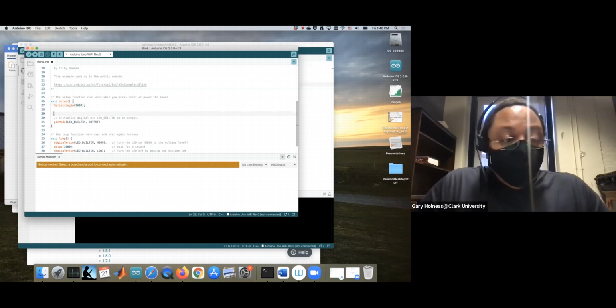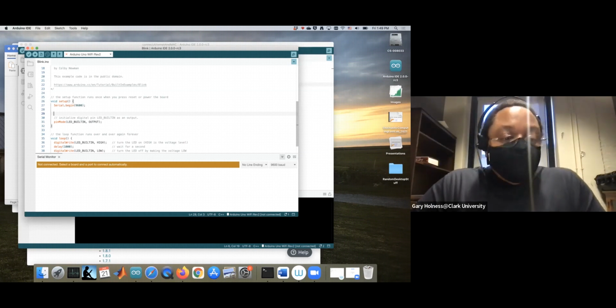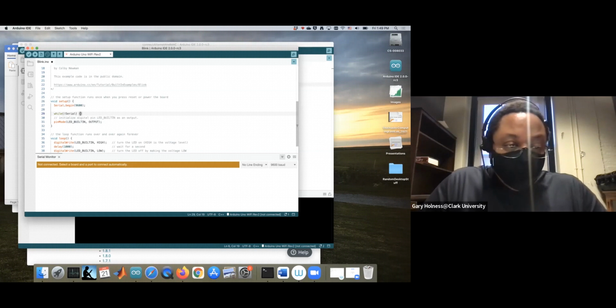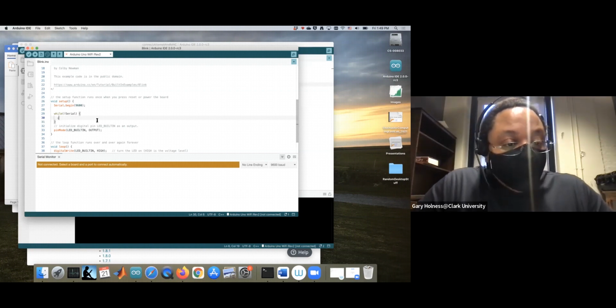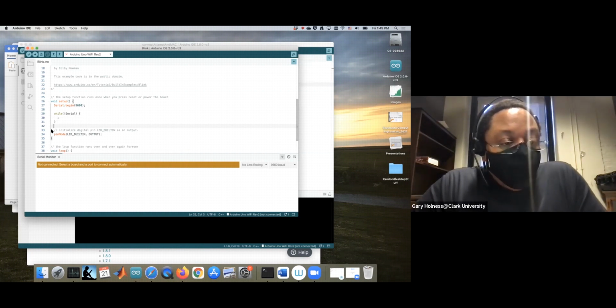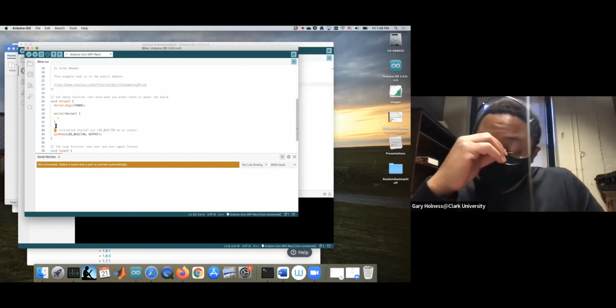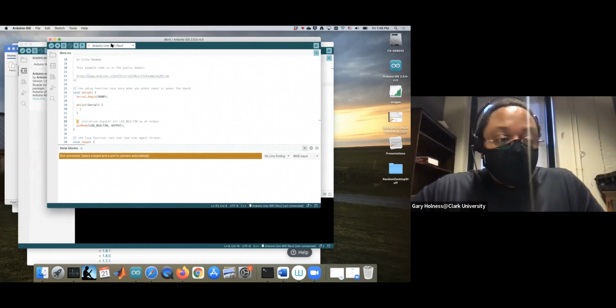So now, once the serial runtime is running, you want your program, your board, to wait until the serial port is initialized. And so we're going to say while not Serial, checking for the runtime coming into existence, we're going to have a semicolon, an empty statement. And so once this finishes executing, when we're on line 33 or greater, the system is connected and able to print and send output to the console.